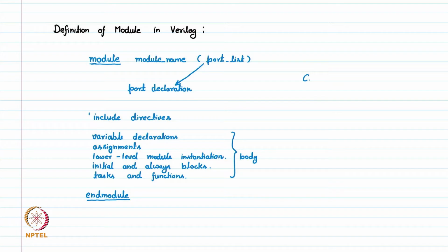For example, if we want to put comments in Verilog which we write only for our understanding, we do not want Verilog to simulate them. So if we want to have a one line comment, we can start anywhere by typing these two slashes.